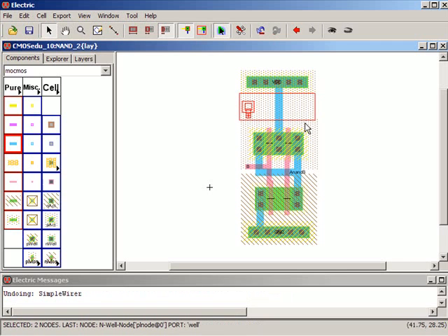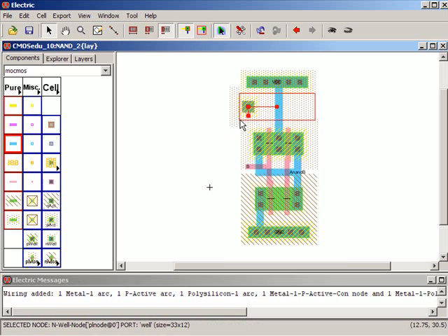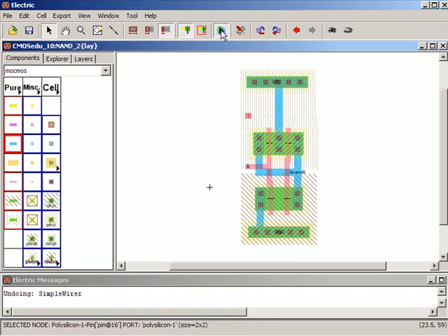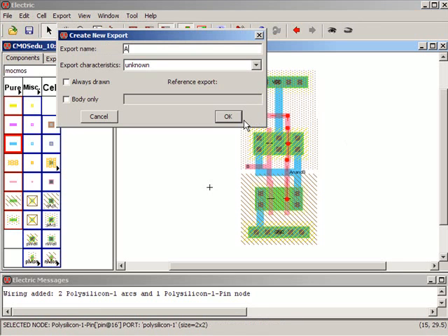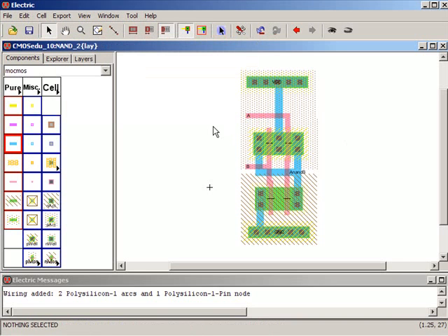Right click. Okay, so this is an area where I'm fighting with that pure layer. So I'm going to go ahead and, Control Z, turn that off. See how turning off the special select helps me so I don't fight with it. So this would be B. So I do a Control E for export, A, and then save it before I go too much further.